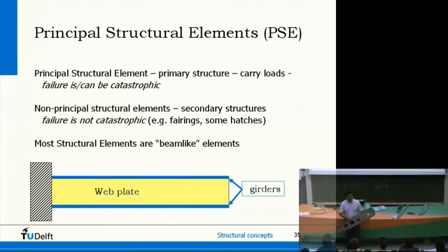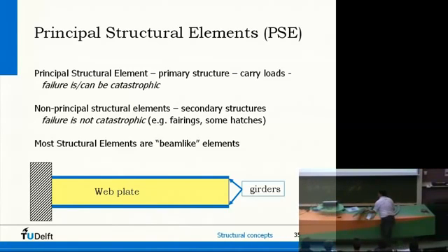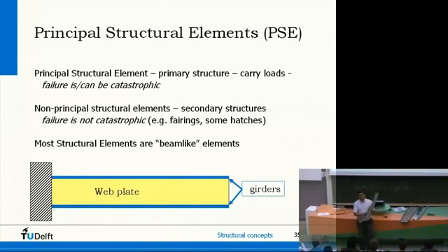In this case you see a lot of holes. Those are for reducing the weight, and also a number of these stiffening elements. You can see them even better on this side. Both the collar here, the edge here, as well as these ones are for increasing the stiffness of this flat surface. But the basic concept, the basic principle, again, is a beam. I have more beams. The frame of an aircraft. Here you have the slots for the stringers to run along with the frame. But again, two flanges, upper and lower, and a web plate in between.